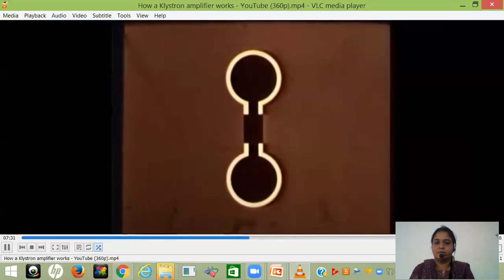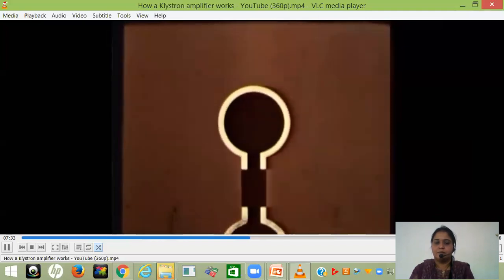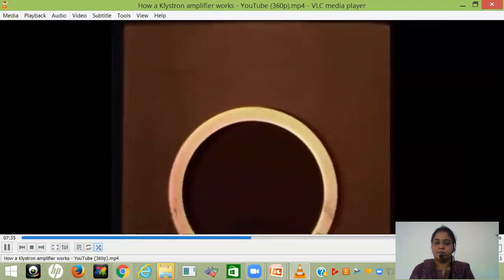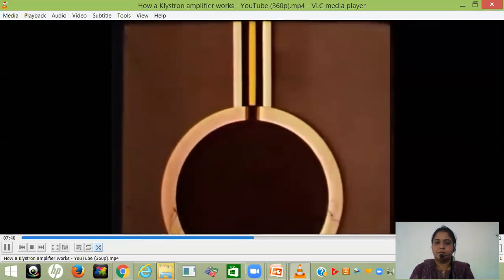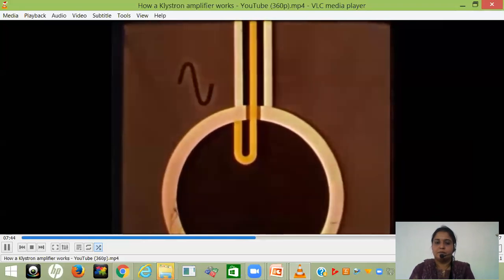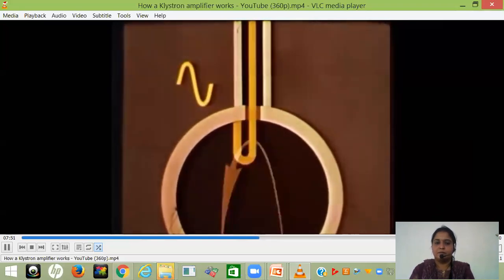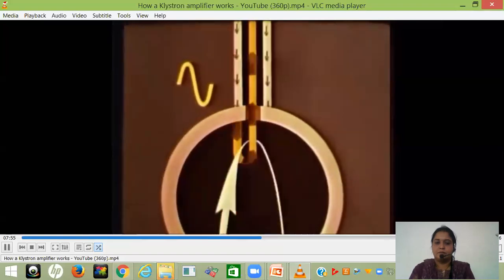The first resonator of the klystron is excited by the external signal which is to be amplified. This signal, often introduced via a coaxial cable, must have a frequency at which the cavity can resonate. The current in the coaxial cable sets up a magnetic field, which in turn brings the resonator into operation. That is to say, that also an electric field is originated.